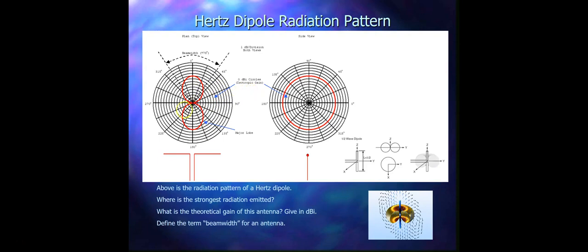And this is the top view of the radiation pattern, and this is the side view of the radiation pattern. In the top view, it radiates best from the side, at 0 degrees and at 180 degrees, whereas at 270 degrees and 90 degrees it is not radiating that much. This is because very little current flows to the end of the dipole, and that's why we see the maximum radiation here and not at these angles.